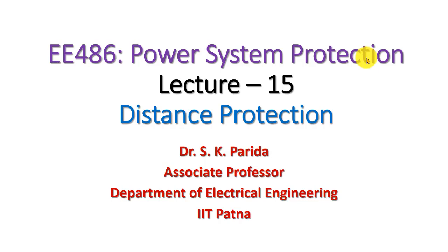We already covered the impedance relay and the reactance relay, which are part of the distance protection. In this lecture we will cover the Moore relay. Let us see what the Moore relay is, how we can implement it, and how its performance compares with the impedance relay and reactance relay. Its performance is not as good as the impedance relay and reactance relay.